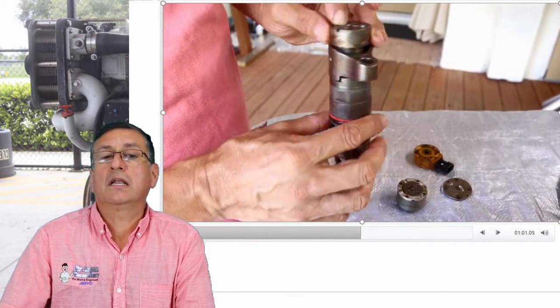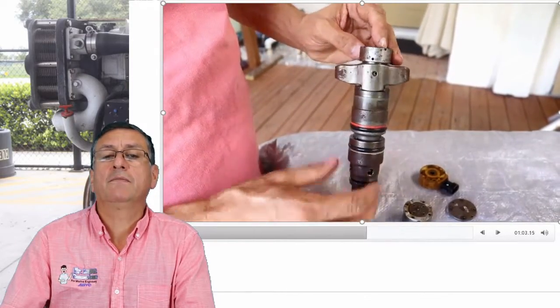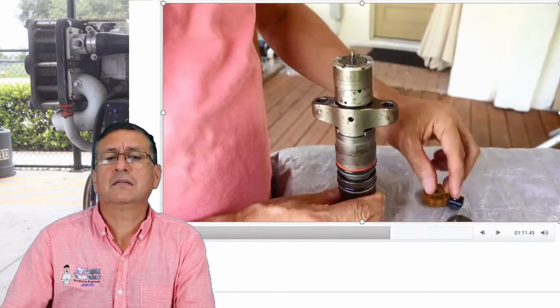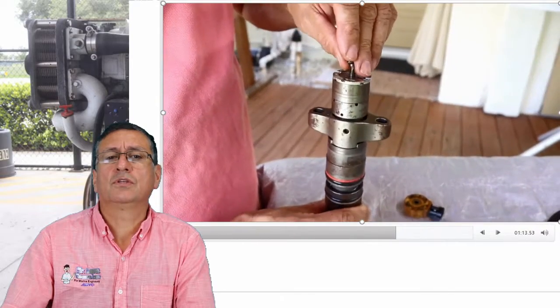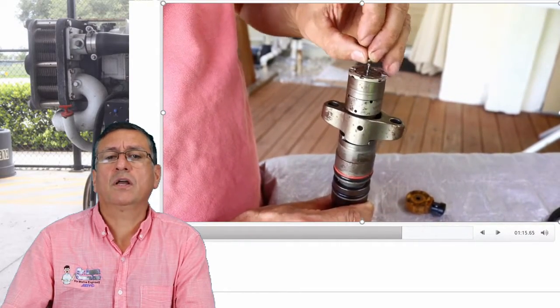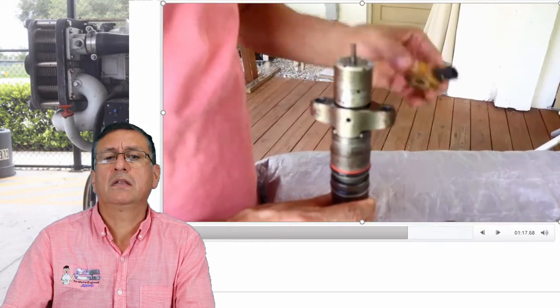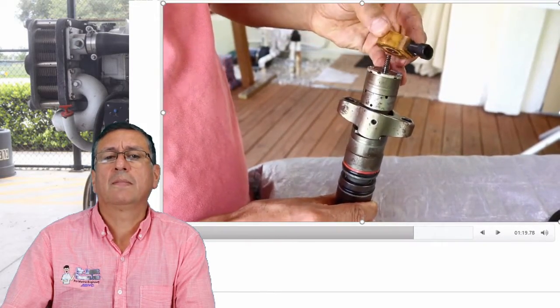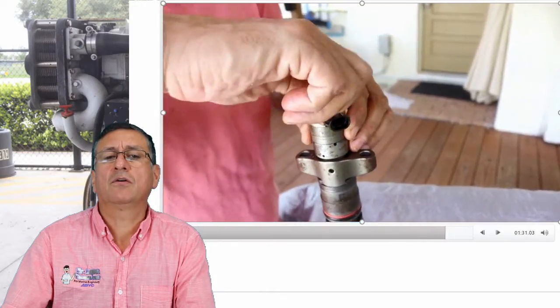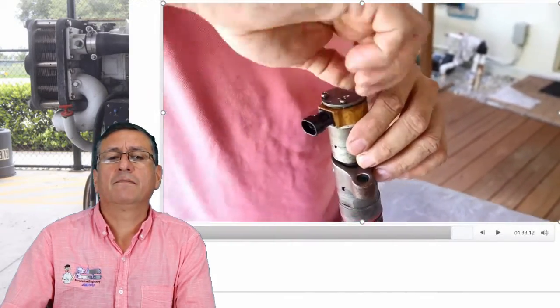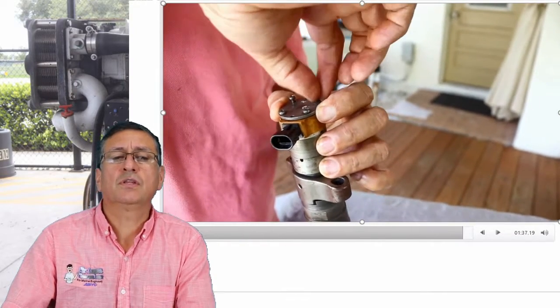Okay, that's the procedure. And you can replace the solenoid. The construction internally is the same. You can replace the body. You put back the solenoid with the spring, with all the parts, and you reassemble those injectors easily. That's the pin, the washer, the spring, the solenoid. It's a simple process. The only thing you need is to be organized, be clean, and the procedure is very simple.